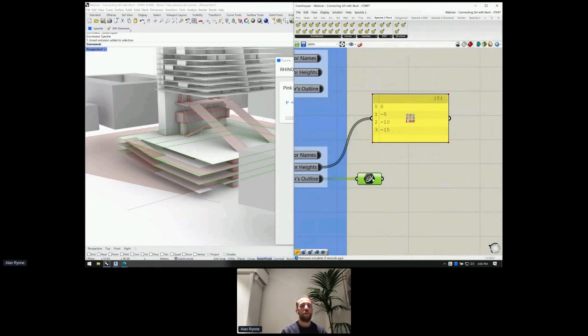So the first thing that we would need to control is, remember when we received from Rhino to Revit, we had these generated levels that we didn't choose to create. They just were created for us by the Speckle connector because each floor needed to have its own level attached to it. It has to live on a level.